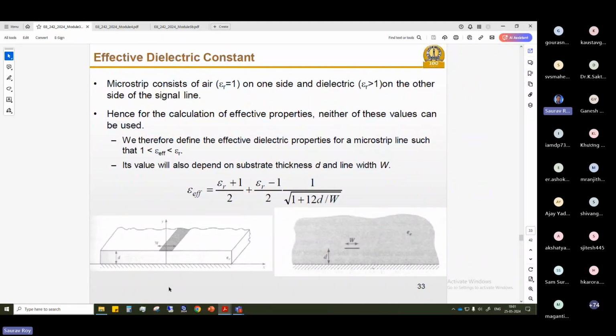And that's why a very important parameter in a microstrip line is effective permittivity. Whenever you have to design a microstrip line, you will be given some substrate, right? From this substrate, let's say you have to calculate the wavelength and phase velocity and all this. All this calculation will not be done through the normal substrate dielectric constant. You have to calculate the effective dielectric constant. You will have some tools in ADS that I will show you, and there are plenty of tools available on the internet also. This website will show you the design values.